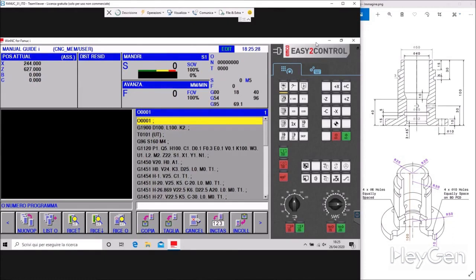I can tell you that in my professional life, as you know, I was a craftsman working in high production. I never used conversational programming. To be honest, I only used CAM to figure out certain points that I struggled to calculate. But in reality, when you're doing high production, ISO is unbeatable because it allows you to fine-tune the program down to the smallest details and optimize production times.